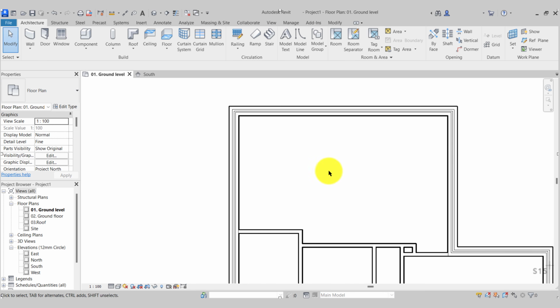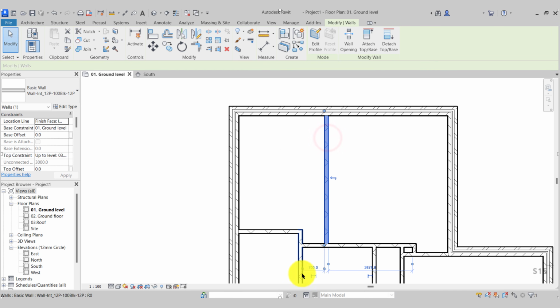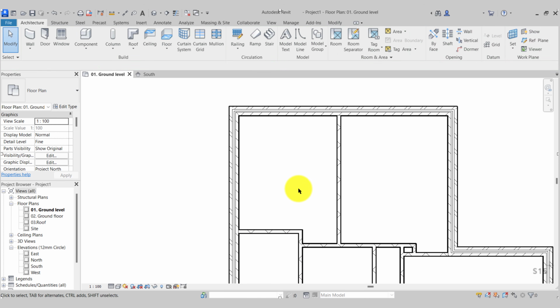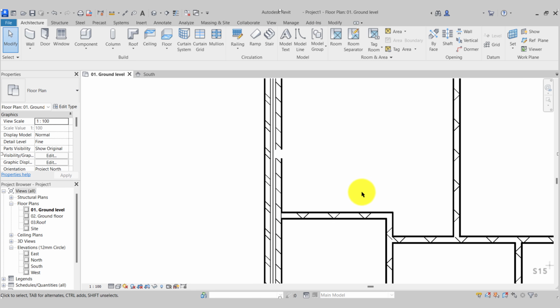We need to close off and separate this to create two new rooms. So we'll draw in our wall, come back to it, select our temporary dimension, dragging it over. It's 3125. And then finally for the internal walls, we'll create this alcove here.